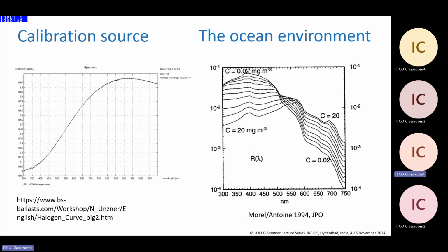Ideally, if you take your sensor back to get calibrated, you could ask them, hey, my typical temperatures are this. Or you could pay for 3 different calibrations, say, please put it in the fridge or whatever, and do one at 15, 25, and 35C, and then linearly interpolate the calibration coefficients. That's what we do with ours.